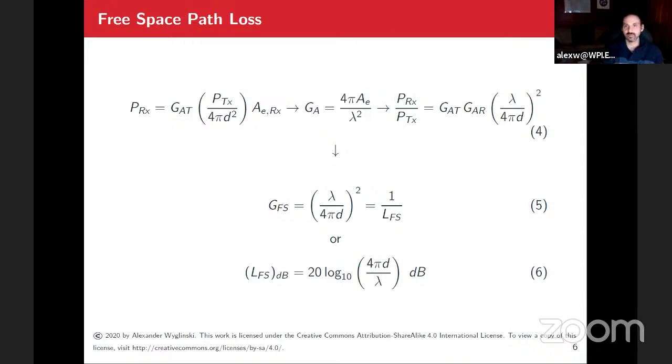So lecture slides are great. Definitely use them as a reference, but really any sort of link budget analysis question that I will send your way for this course will focus on this concept. So you have your transmitter. What is the gain of the transmit antenna? Plus, if there's any sort of RF hardware that amplifies the signal before it gets sent over the propagation medium, that will have a gain. Then there's the propagation, which is really a loss.